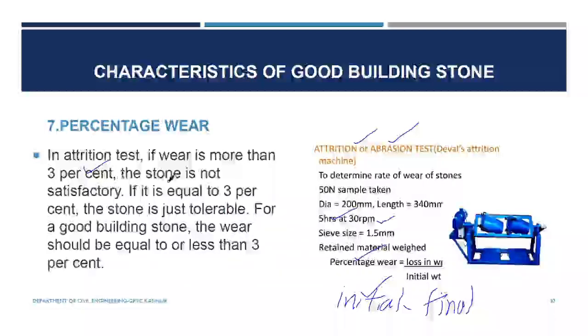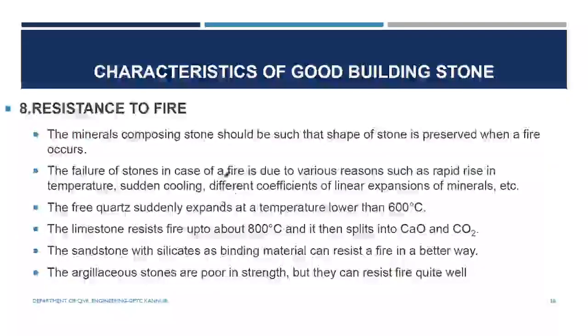That is 3%. If wear is more than 3%, the stone is not satisfactory. If it is equal to 3%, it is satisfactory. For a good building stone, the wear should be equal to or less than 3%. Next, resistant to fire.